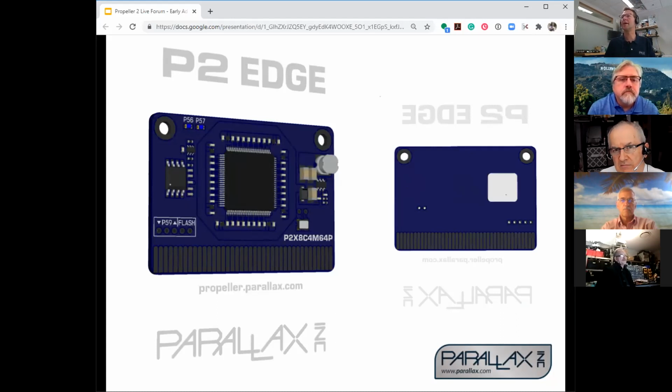Okay, so it's got a SPI flash 16 megabyte, in parentheses it says 128 megabyte, a 1.8 volt 2 amp switching power supply, a 3.3 volt 300 milliamp LDO per 8 IOs, 20 megahertz crystal oscillator, 2 LEDs, which are buffered on pins 56, 57, all IOs, power, reset, etc., broken out to the 80-way edge pad, where you can connect 5 volt and ground.